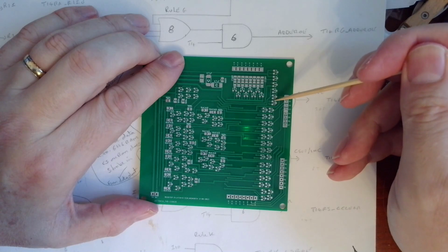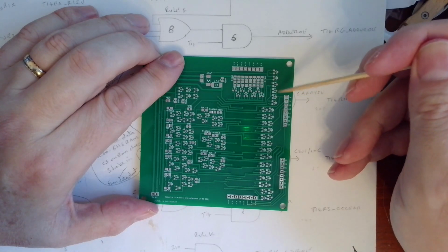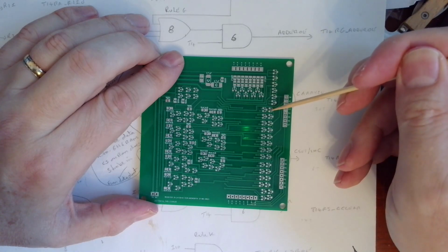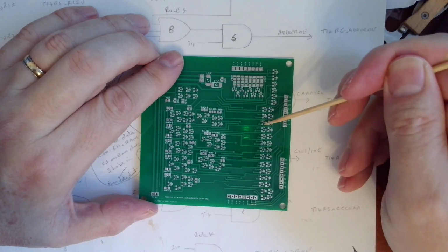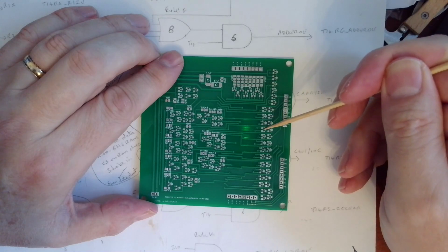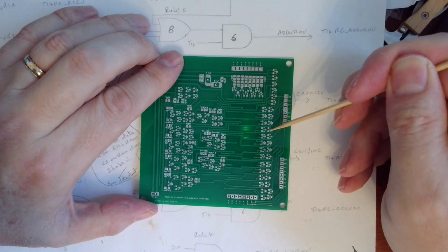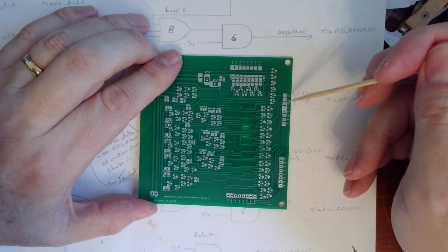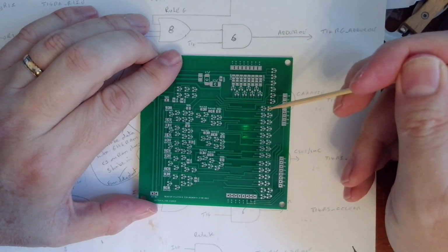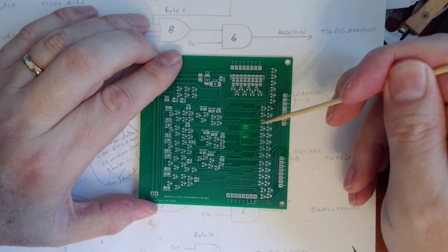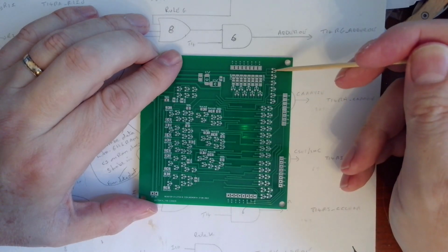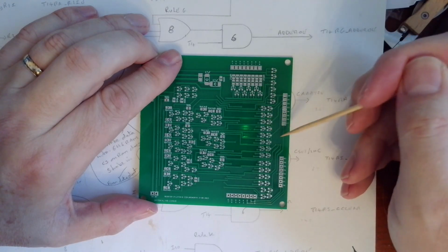And this transistor and this one are the supply transistors to this inverter. These two are the supply transistors to this inverter. These two transistors are the supply for this inverter, and so forth all the way down. So each output on the data bus going out has got its own pair of supply transistors switched by the control signal. So they're all isolated from each other.